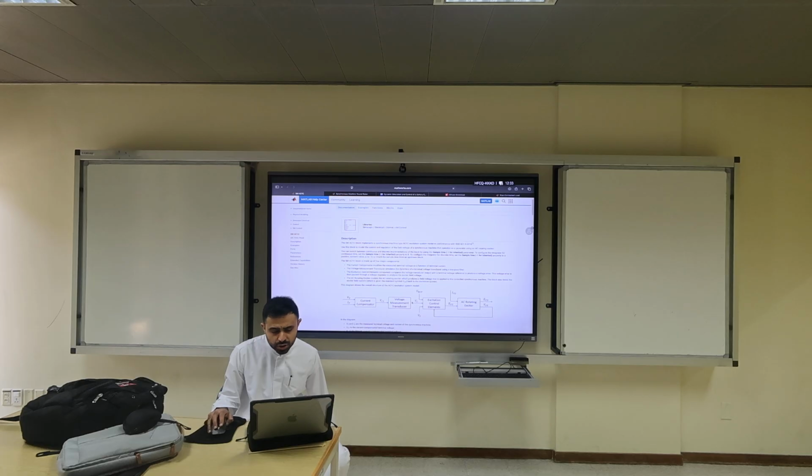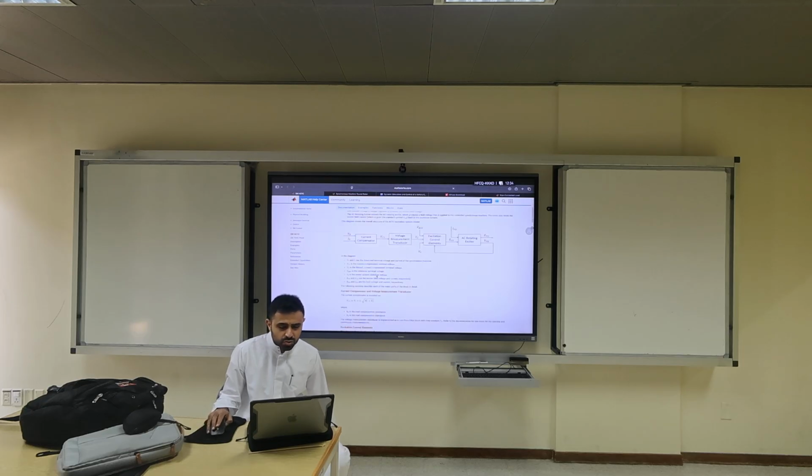If you notice here, we have V terminal and I terminal. We have the current compensator. We get VC1. We have the voltage measurement transducer. We compare it with the reference and VS. This is the excitation control element. We get IF. Then we have the exciter itself. And then we get EF, this is the DC component. And then we get the feedback reference. So these are complicated things. This is the block diagram.